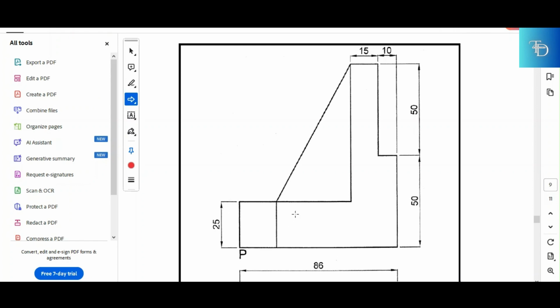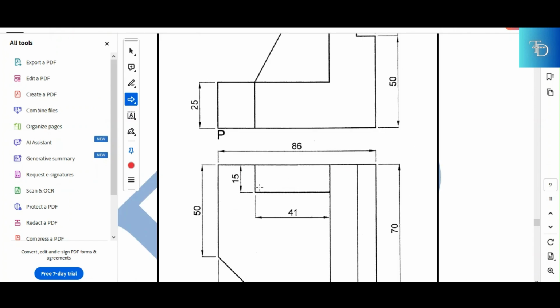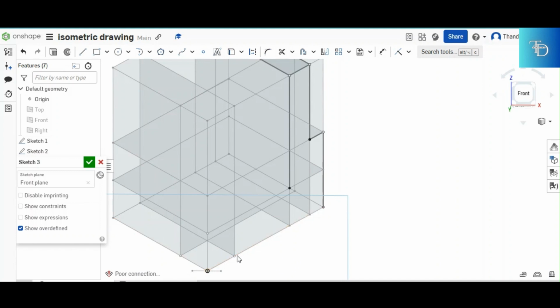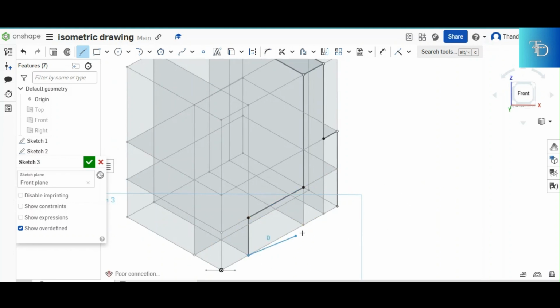But now, remember that we have that chamfered shape right there at this point. That's why there's this line right there. So let's go over and put that straight line right there, which is the distance from point P, 20 millimeters in. And then you go back, there is our point P right there, there is our 20 millimeters in, and then we have that distance right there that is going up to the 25. And then from that point, that's where it meets with the previous outlines. And then obviously it closes at the base like that. So now you were able to come up with the shape.